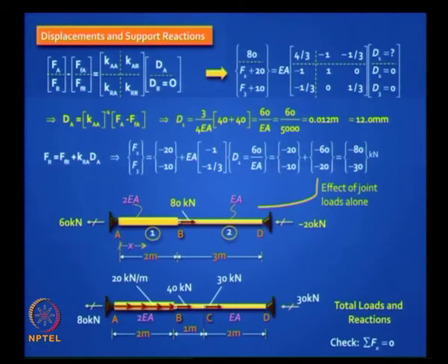What is left now? You are almost done. You need to find the internal forces. How do you do that? Fixed end forces plus Ki Ti times D. You have to be careful about D, I will explain how.